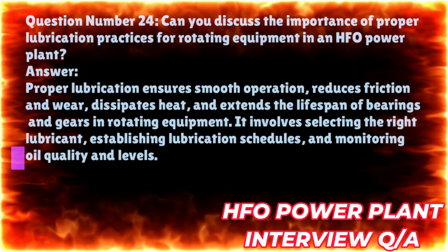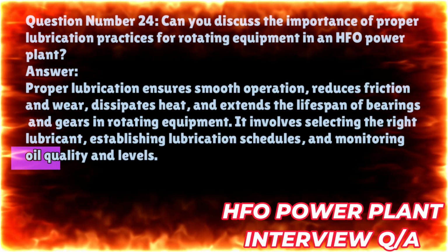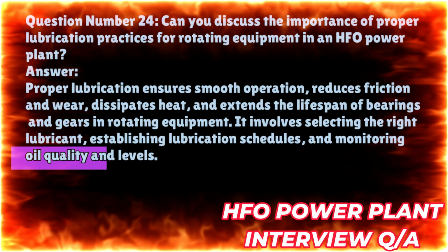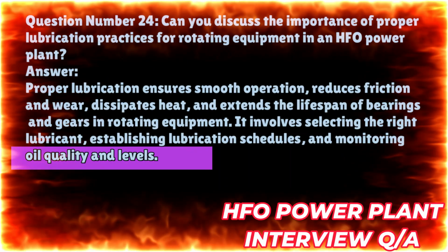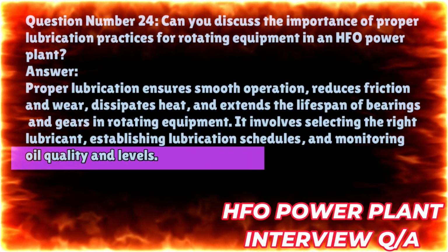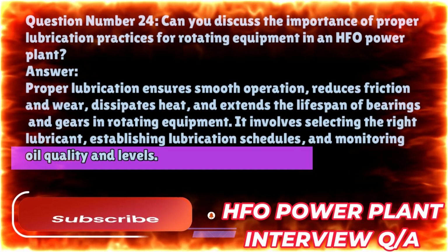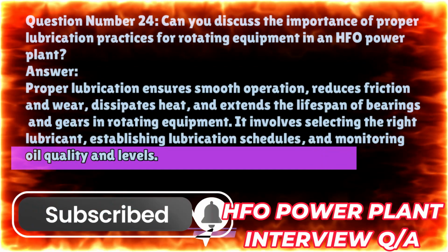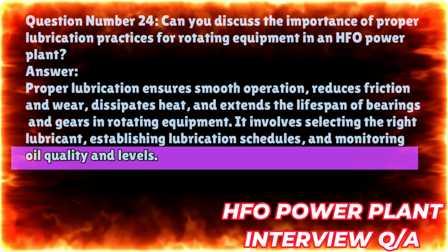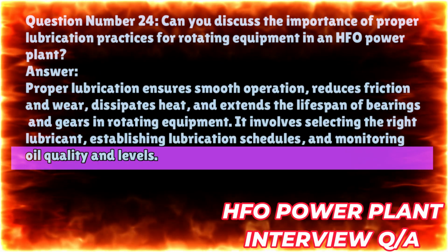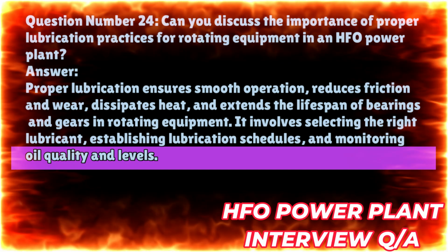Question number 24. Can you discuss the importance of proper lubrication practices for rotating equipment in an HFO power plant? Answer. Proper lubrication ensures smooth operation, reduces friction and wear, dissipates heat, and extends the lifespan of bearings and gears in rotating equipment. It involves selecting the right lubricant, establishing lubrication schedules, and monitoring oil quality and levels.